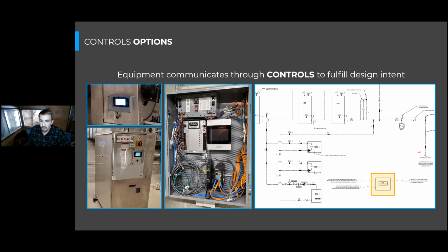There are a lot of different ways to implement these controls, and I will get into a little bit more detail a little bit later today. But at a high level, you want to keep the heat pump water temperatures and the on and off set points, as well as the piping configuration and the locations of the temperature sensors in mind while you design your control sequence in coordination with the manufacturer and designer.